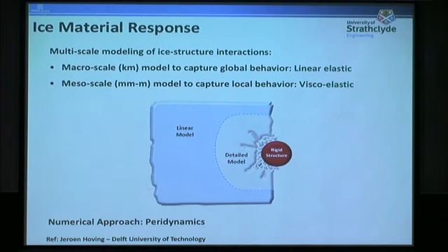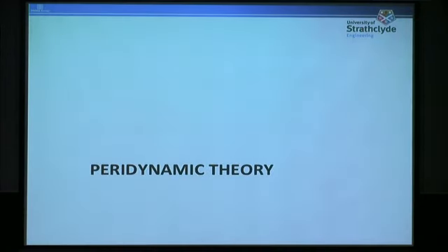And to obtain such a scenario, you would like to use a new numerical technique which is called peridynamics. So next, as I mentioned to you earlier, I will give you some information about what peridynamics is all about. So peridynamics is basically a new continuum mechanics formulation. Why is it new? Because we are using a different set of equations. We are using integral equations as opposed to the partial differential equations that we normally use in classical continuum mechanics.